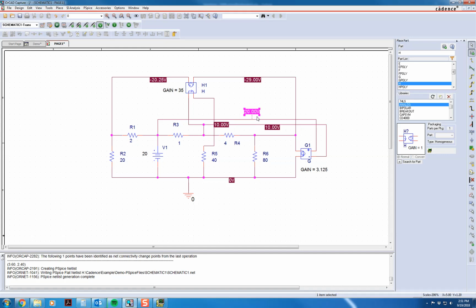But you can again turn the currents on. Now when you start turning some of these on, because we've got wires everywhere, it can be a little difficult to see where everything is. So you see how I did that here, I pulled it away. And now let's look at this here. It says that there's 250 milliamps coming in, and when this says negative 250 milliamps, that's because it's also looking at it going in. And that would make sense, right? Current going into a node has to equal the current leaving the node, or if you're summing the currents going into a node, it's got to be 0. 250 plus negative 250 is 0.